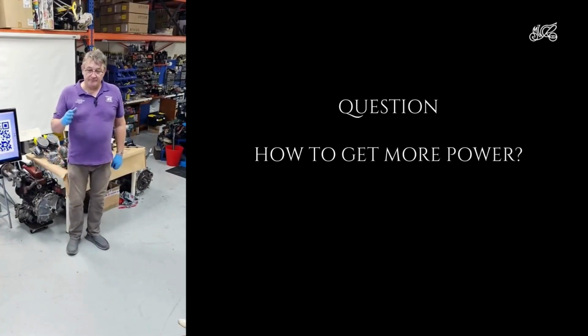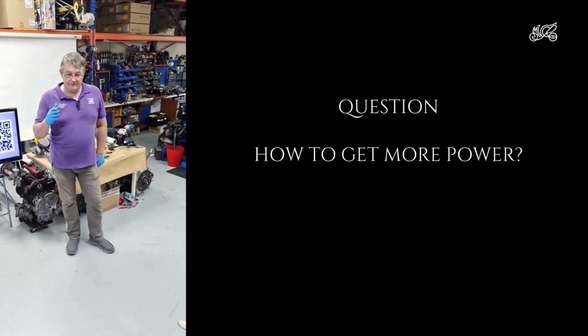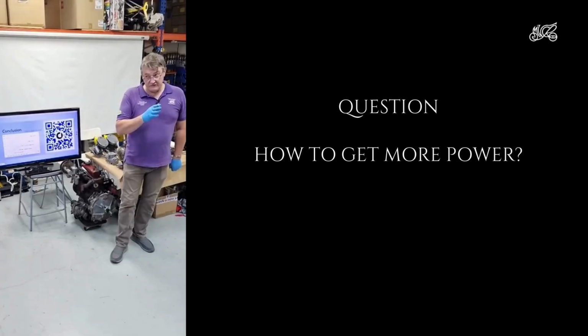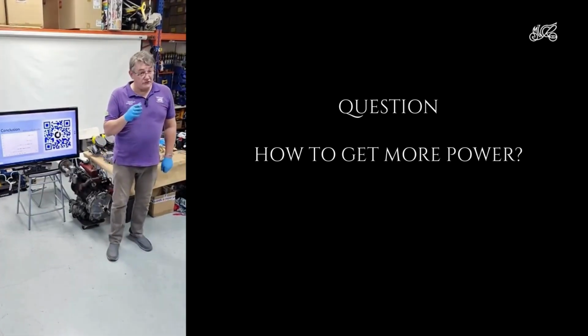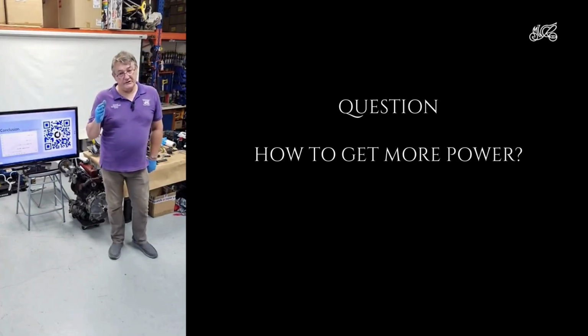Actually, engine temperature depends on mixture. So as the mixture goes leaner, the engine runs hotter. That's why if your engine runs lean for too long, you will melt the pistons, because it runs hotter and eventually the pistons will melt. The engine also runs hotter if the ignition is retarded.